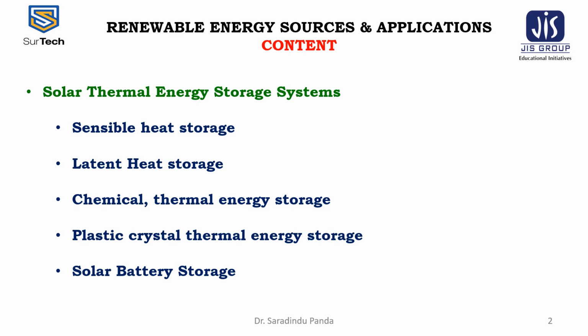There is another criterion for the thermal storage depending on the time involved, that is short-term storage for a couple of days or the long-term storage over a period of months. This is also called the seasonal storage. The criteria for low and high temperature heat are not specified. Usually the temperatures below 100 degrees centigrade are named as the low temperature, and above 100 degrees centigrade it is called the high temperature.